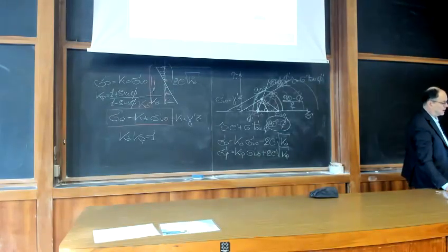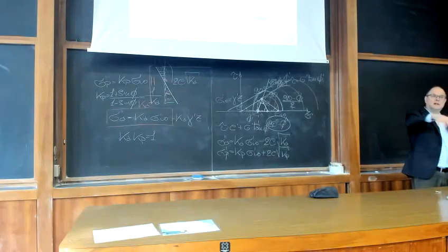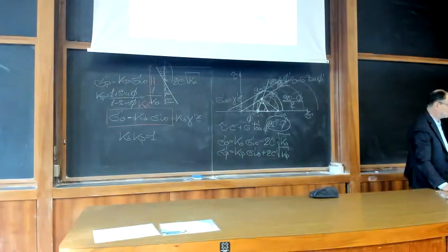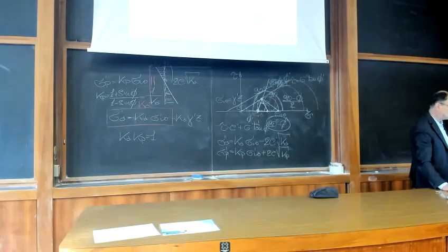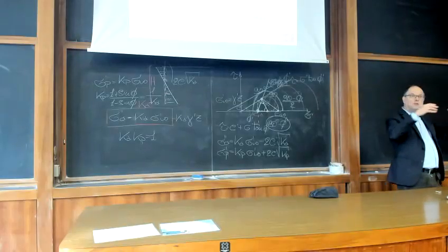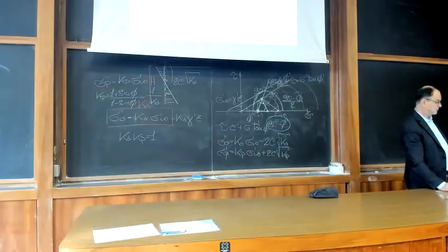Now, of course, if you have different columns, you might have a unique enlargement. You have single footing, which is not square, can be rectangular or can be any shape. This very much depends on the shape of your structure and the distribution of the applied loads.